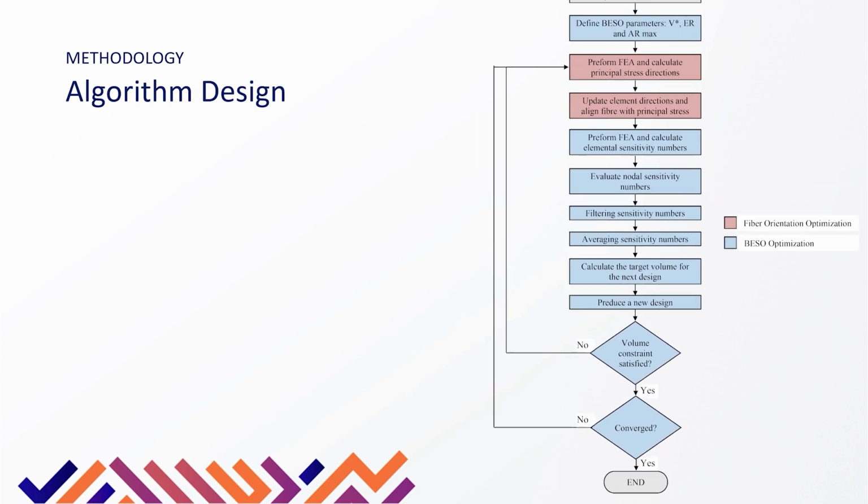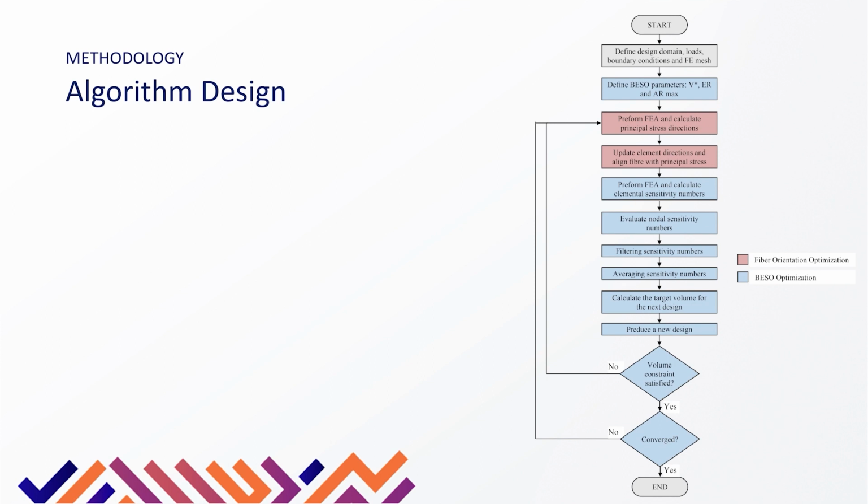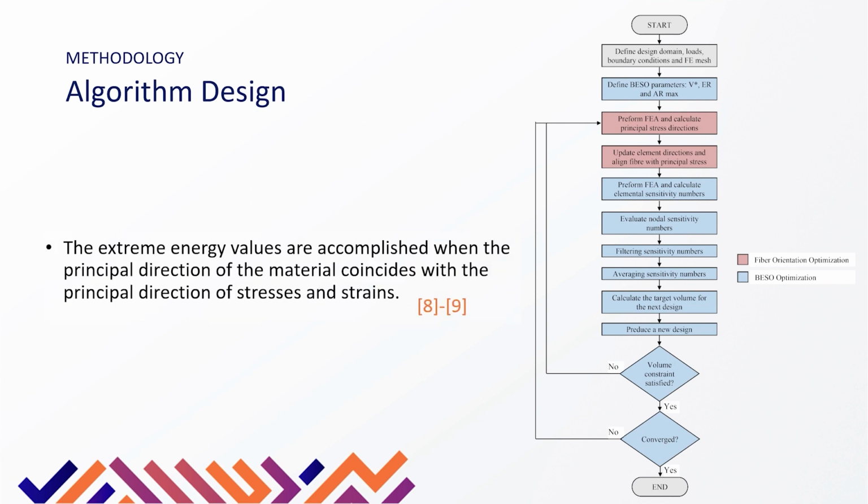So what we did here is let BESO take into consideration the orthotropic nature of the material and produce the optimal configuration for fibers, as the extreme energy values are accomplished when the principal direction of the material coincides with the principal direction of the stress and strain.